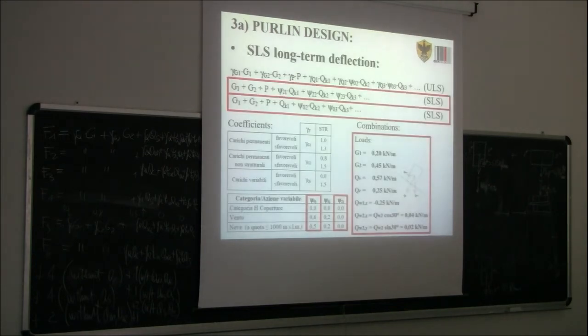So these are the values of the loads, G1, G2, QS, QC. Again, we have QW1Z, QW2Z, and QWYZ. QW1Z is not considered because it's basically favorable. We should consider this only if it was so big to basically cancel out all the permanent loads.